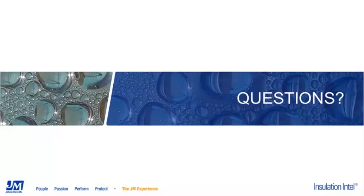Well, the factors that determine the thickness, there are a lot of them. The simplest one, and it's even complex, is the thermal conductivity of the insulation. And Kathi and Meredith talked about that. Certain insulations are better insulators than others, and they require less thickness. Phenolic, in the ones we discussed today, phenolic and PIR the least, cellular glass the most, with fiberglass in the middle. So that's the simplest one, and it's still complicated. The other factors that influence the thickness required, well, let's start with the energy codes. Those are sort of a de minimis level. You need at least those just to comply with the codes.